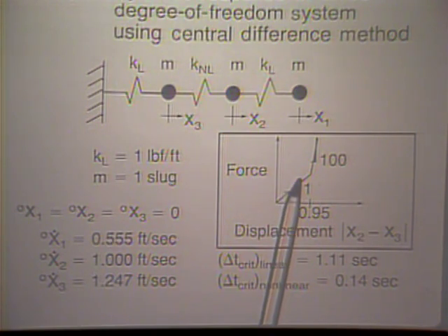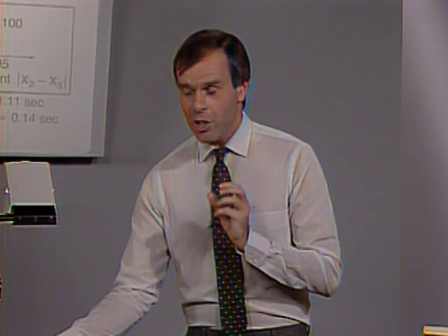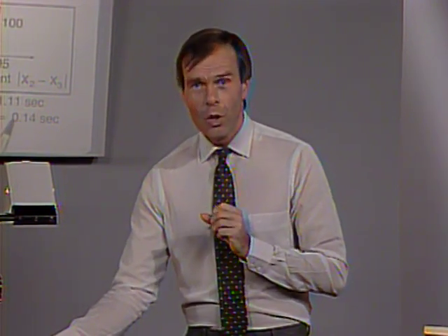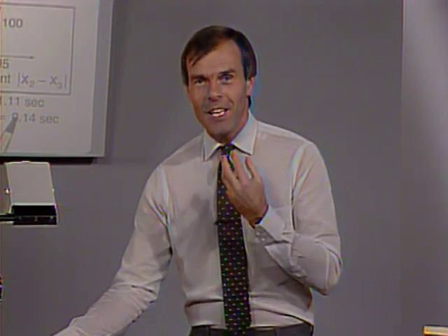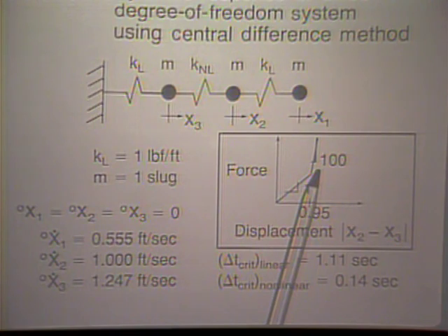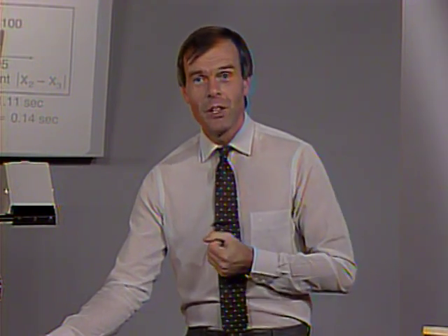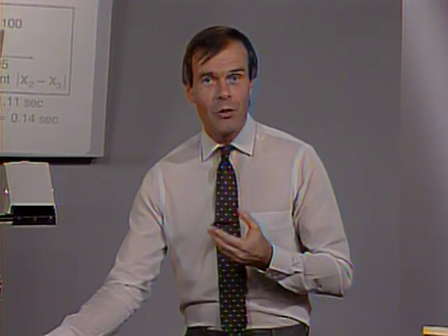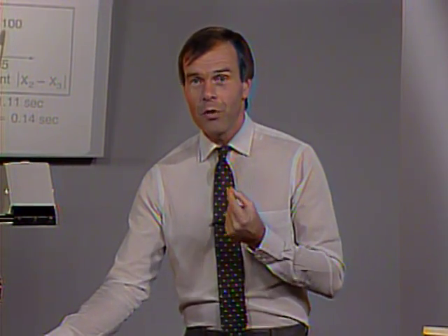If your time step that you use in the time integration is then larger than that value, you have an instability for just these few time steps, and that introduces an error in the solution, which, if you don't have a comparison with an exact analytical solution, will of course be an error that you not necessarily will see directly. And that's one of the important points.